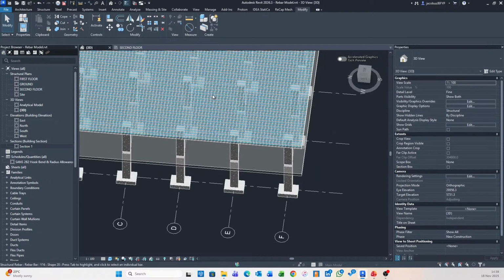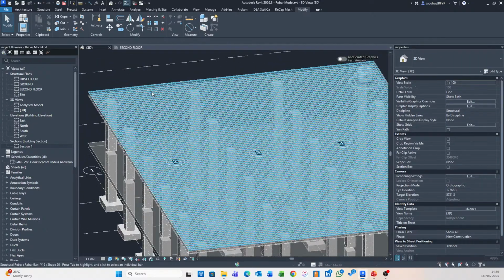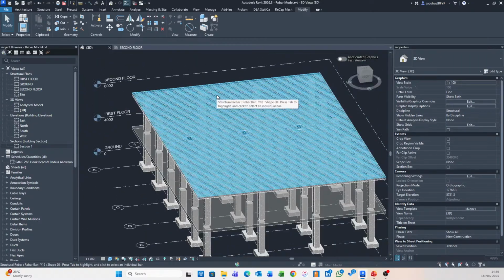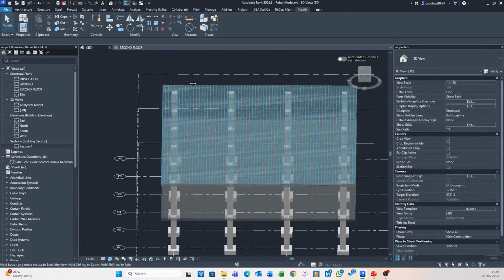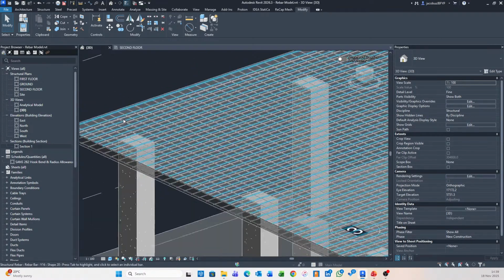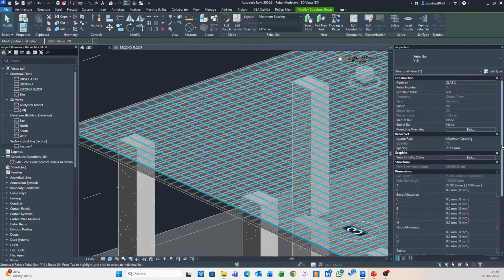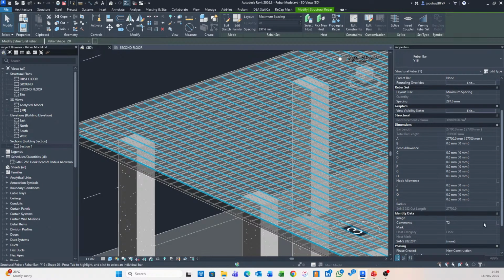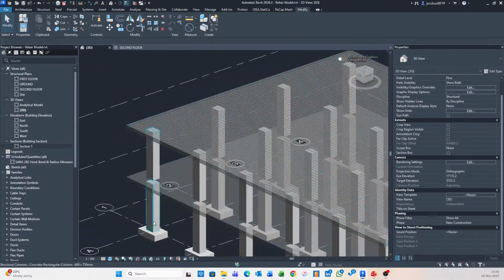Okay, so now we need to get to the process of actually scheduling our rebar, and there are some tricks. My recommendation is starting with the basics and then systematically adding to that. What I want to check here though is, have we defined the partition? Yes, we do have the partition defined. Okay, that's perfect. We don't need to set that actually to anything, because the SANS 282 cut length is calculated off of the A dimension anyway. So it's quite easy with these straight bars.